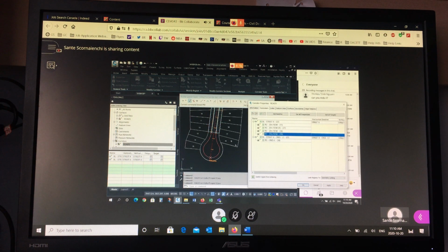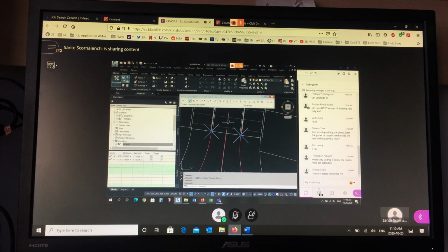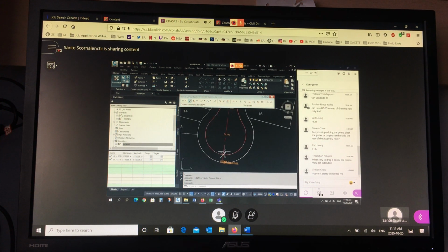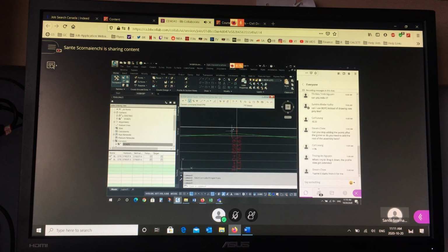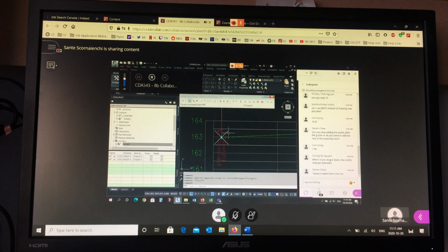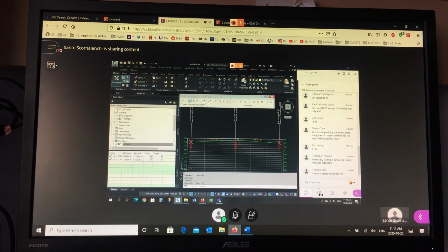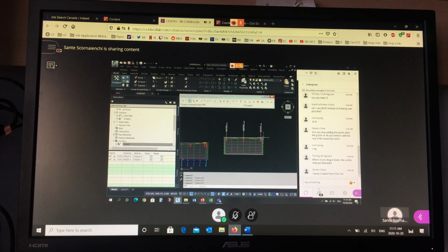Right? If I ever need the, like right now, if I turn that off, the elevation of these 2 points may or may not show up in the profile because they're right on the edge of the data. And this one here has no elevation. Let's see what happened to the profile. See, that point is gone. That projected point is gone. This point is here. This point is here. And the one in the middle is gone. Why? Because there's no surface there. Right? So it has no way of getting its elevation.